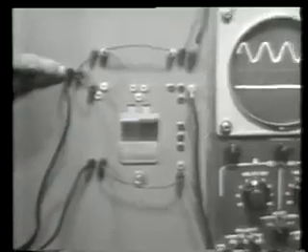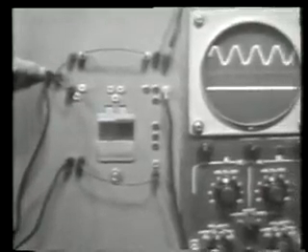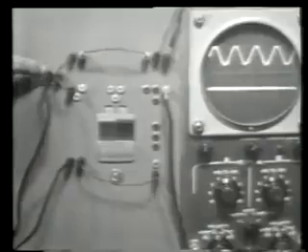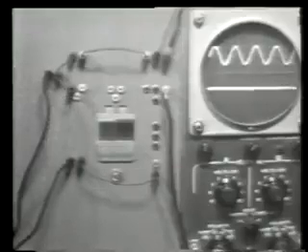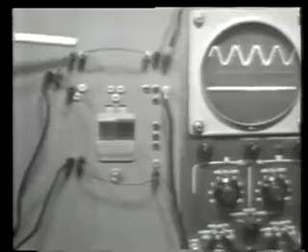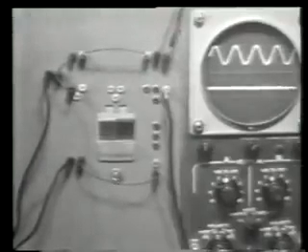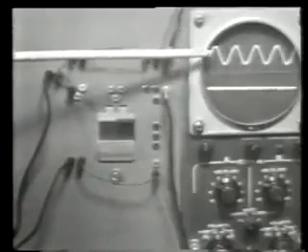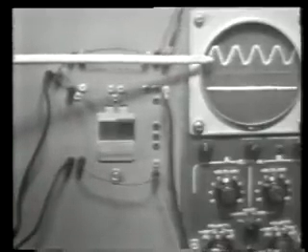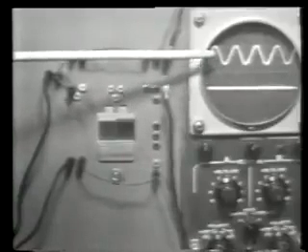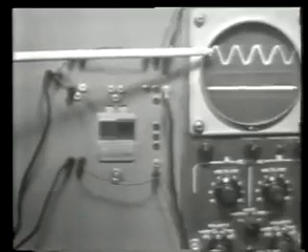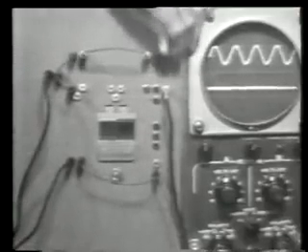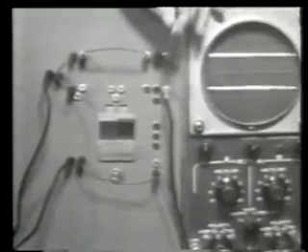But the output voltage is fixed at 10 volts and will be supplied to the trainer from this test point up to this connector. Now from this point, the 10-volt signal is supplied to two places, the upper connection here and a lower connection here. Now the upper connection goes directly over to this point, and as you can see is tied directly in to the A trace or the top trace of the oscilloscope. Now this displays the output from the signal generator at all times, the top trace of the scope, and is connected with this connector to this point.